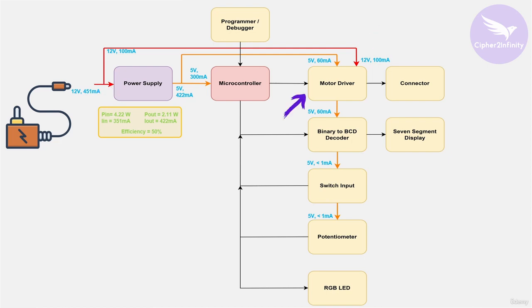So this motor driver block is going to take power from the output of system power supply, and also it's going to take power from the external power supply. Okay, the reason is one power supply is used for the internal operation of the IC, and another power source is used to drive the motors which are connected to this motor driver IC. Okay, so I hope that this particular point is clear now, and also I hope that now it's clear how the different blocks are powered.